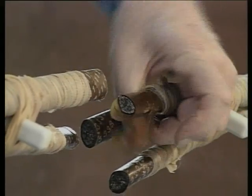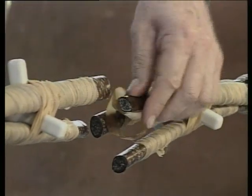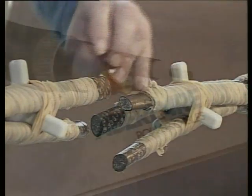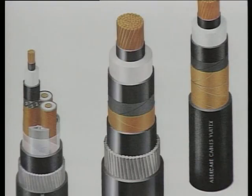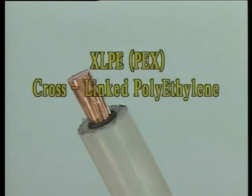Other insulative materials include resin-impregnated paper, as seen here in this medium voltage cable designed for undersurface installation. A material called XLPE is nowadays becoming more and more used, especially in the voltage range of 11,000 volts and upward. Commonly called PEX, XLPE, or cross-linked polyethylene, is an excellent insulative material that is also able to withstand far higher temperatures than other types.